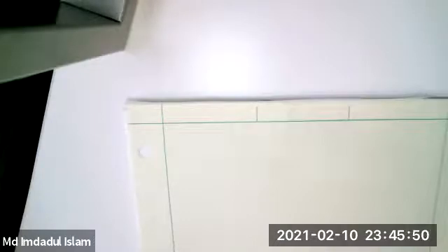There are some extremely stubby, small beams where they're really not beams, actually. The so-called height of the beam exceeds its length, so it's really acting like a plate. But if you start using beam theory, occasionally those shear stresses in the middle of the beam can be comparable, because the bending moment can be very close to 0.